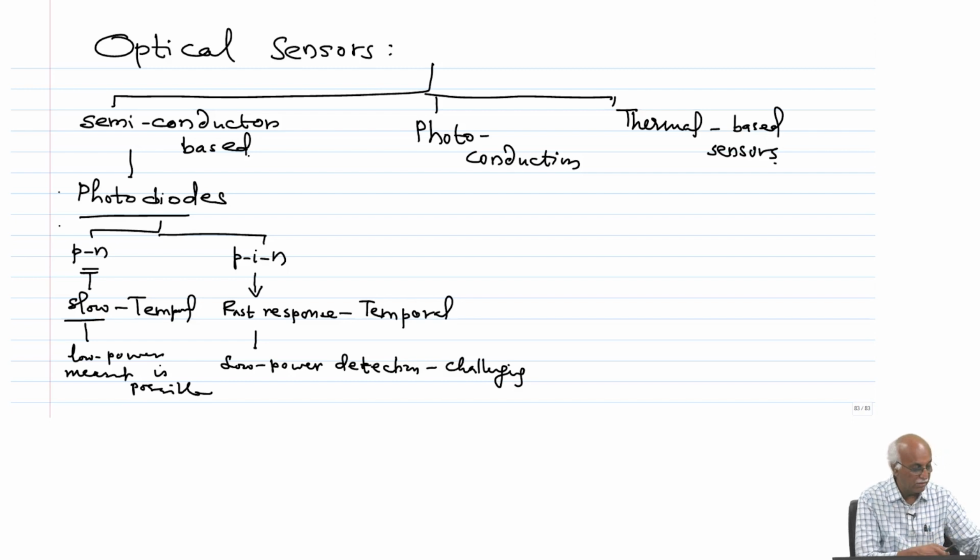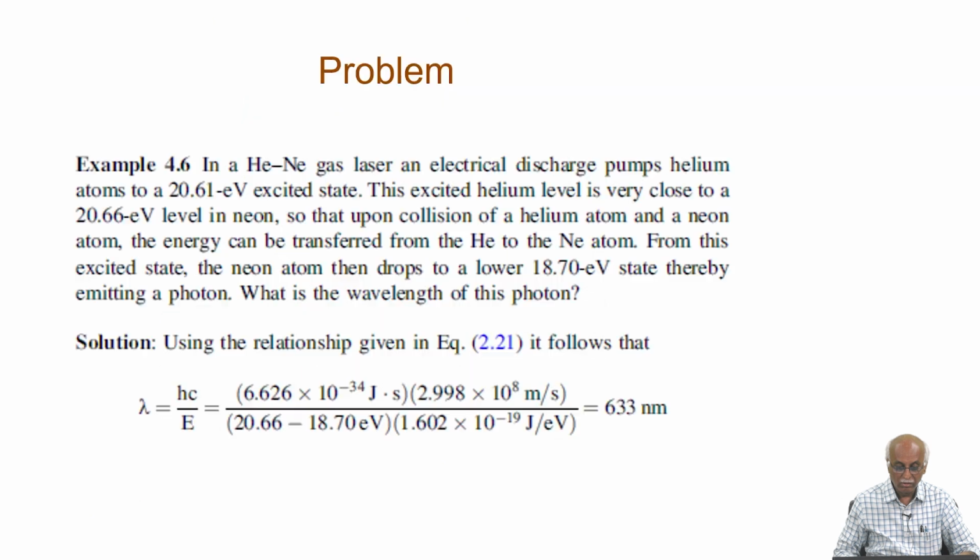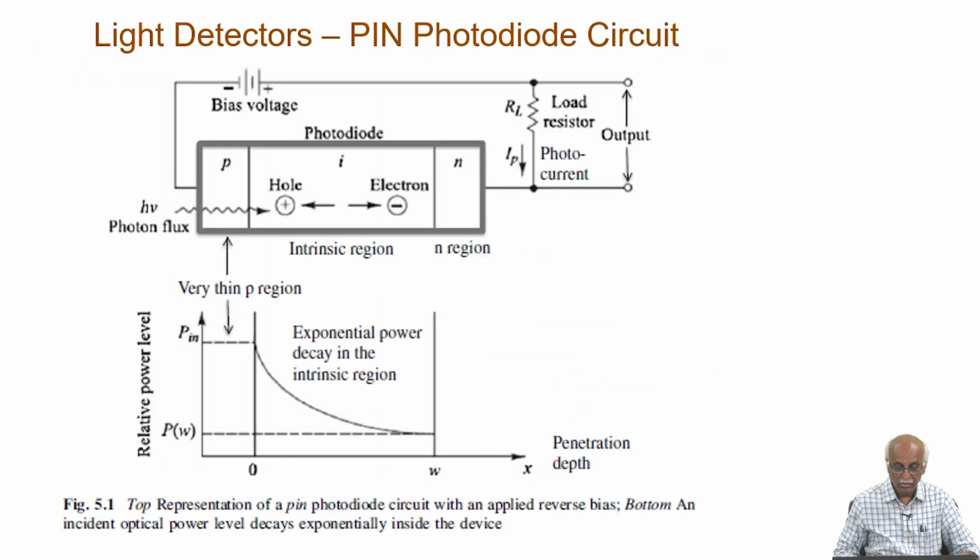And we were just talking about, in case of a photodiode, let us say PIN type, where the intrinsic region is there, when photons pass through, they will dissociate, and holes and electrons will go, electrons towards N, holes will travel towards P.